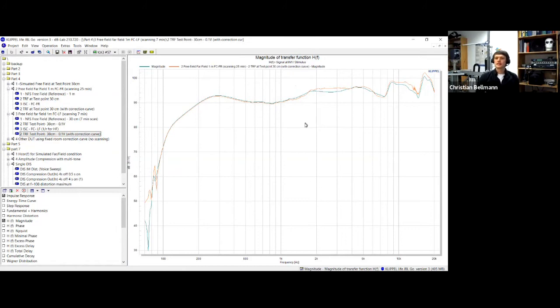So yeah, and this is actually the difference where we now make an assumption. We say we're expecting that we are in the far field, but we see some small near field effects here. So this is interesting. If you're making assumptions like the 1 by r law, on one side you have to ensure you're in the far field, or you have to live with these small limitations here.